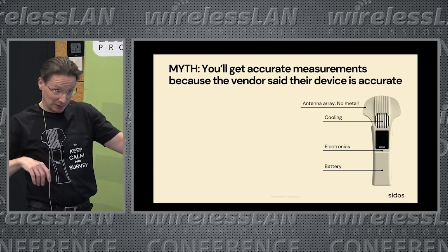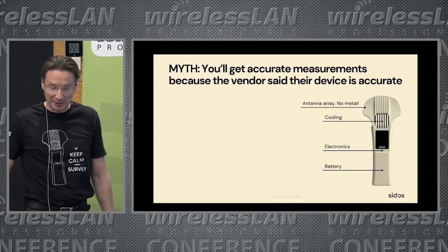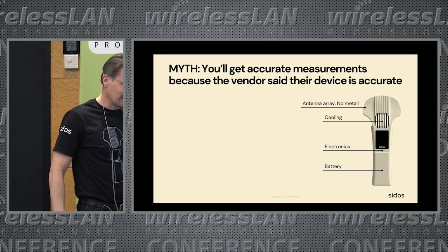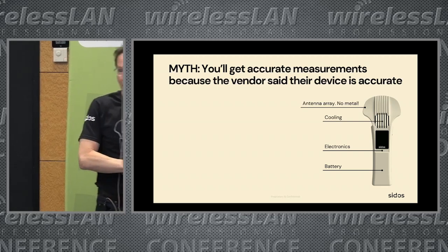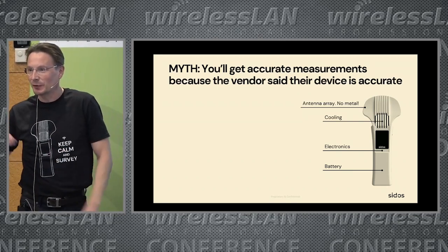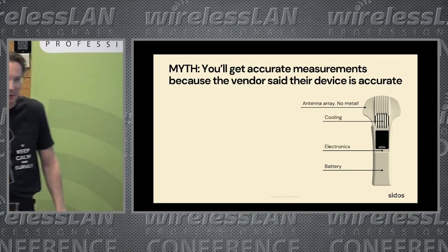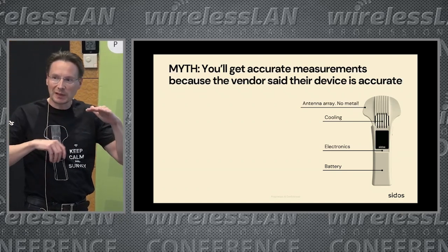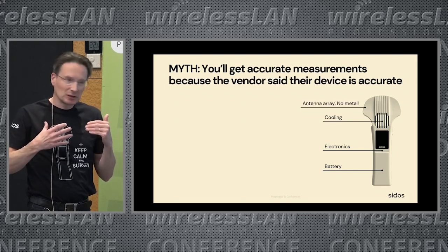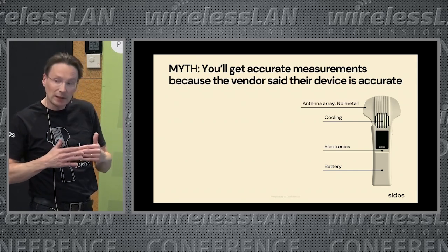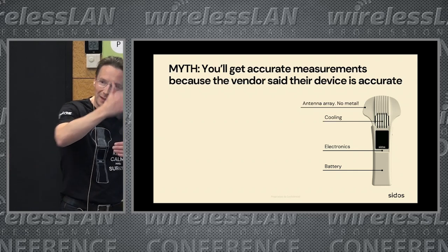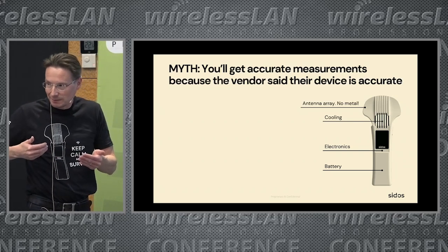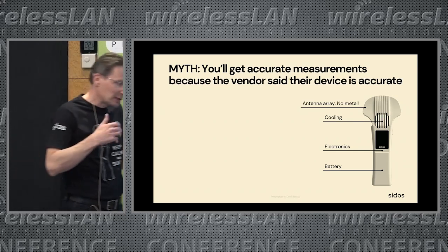I was doing the antenna stuff yesterday with Jim Palmer, and it's a great one if you want to do it. You learn amazing things. But I'm telling you that if you place antennas close to a big ground plane, it's almost impossible for an antenna to hear equally well towards the open space and through a grounded copper plate. So that's a bit of a challenge.